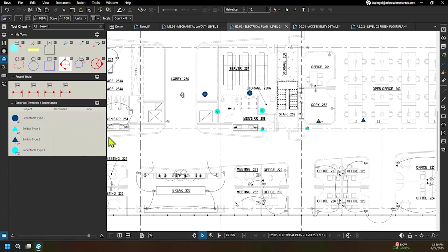And you might have also noticed when I clicked on this little gear icon that you also have the ability to export. This is what I brought up earlier. First, what we're going to want to do is save it. So click on that save button, and then click on export, and it will give you the option to export it just as a .btx file, which you can share with your colleagues, put on a shared network drive, or just send to them via email. All they have to do is double click it, and it will be added to their Bluebeam profile.